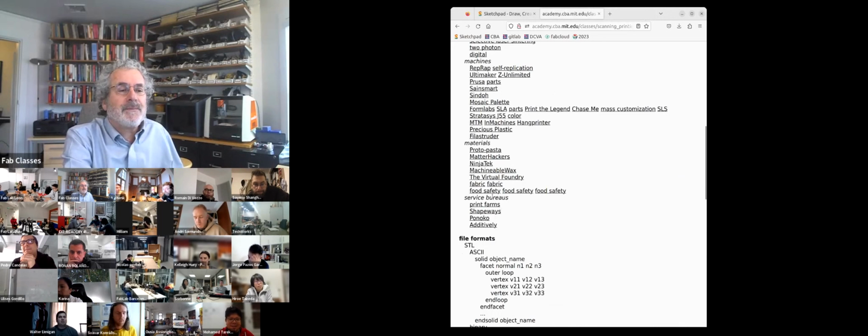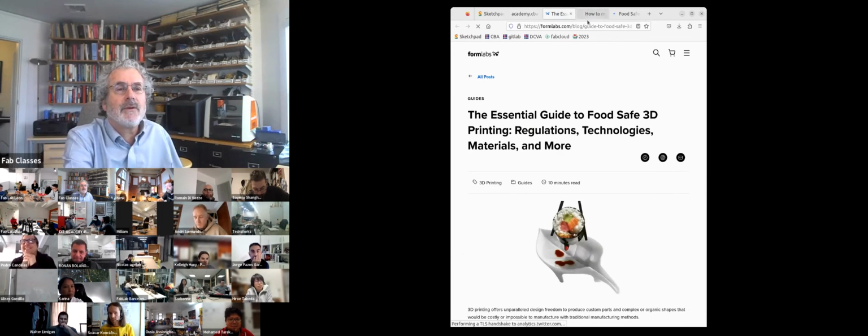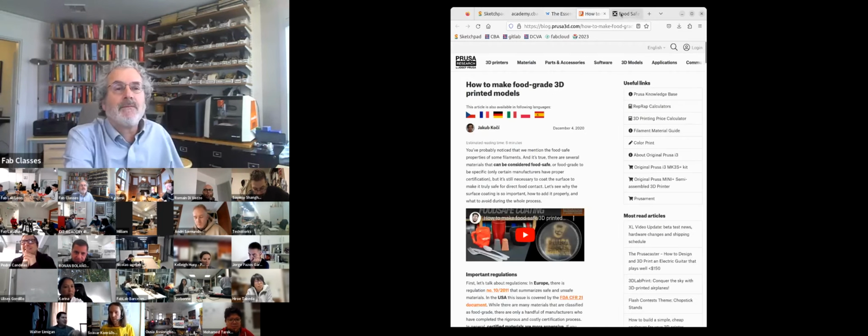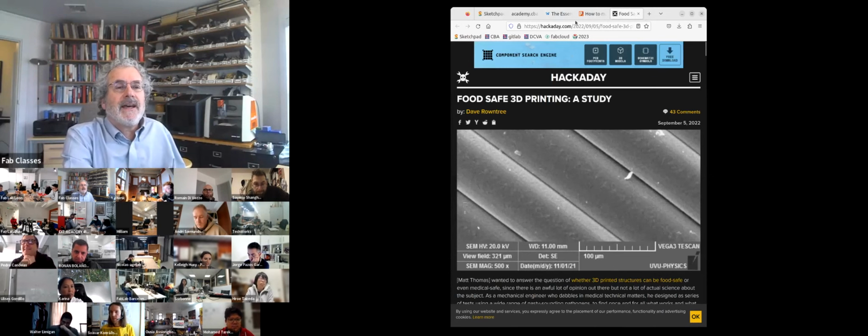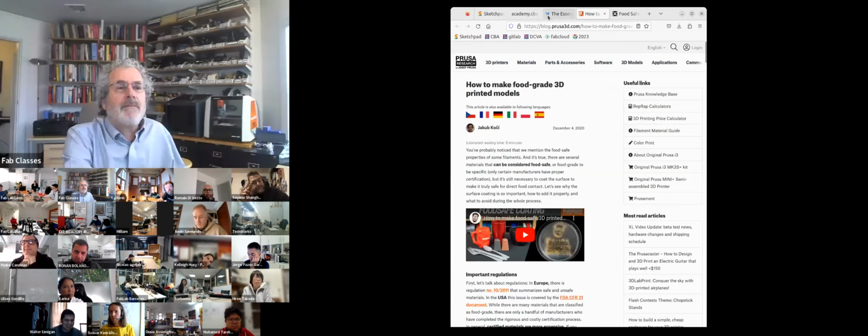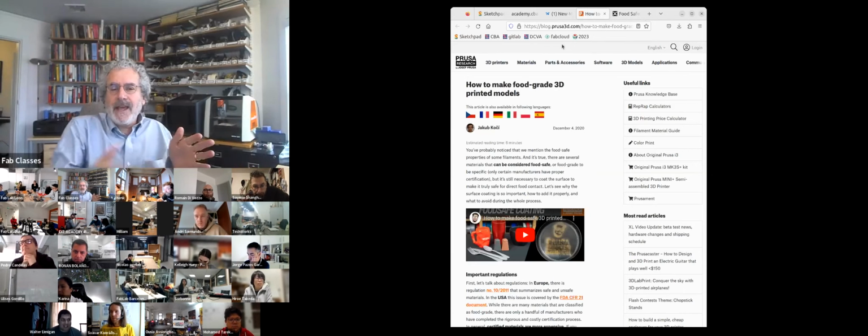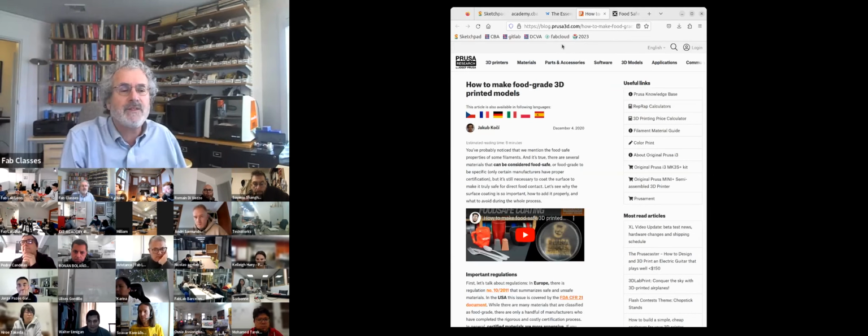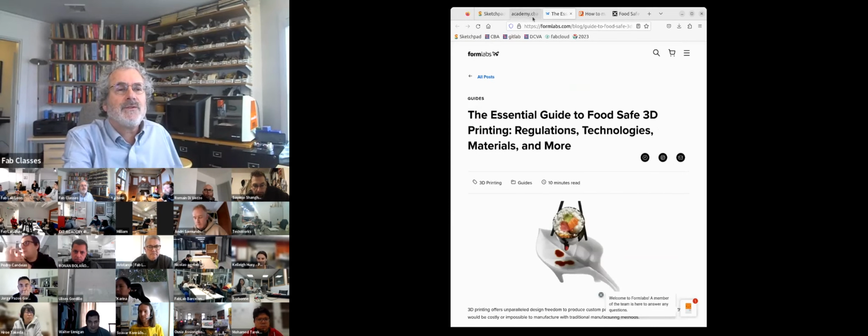Then food. You need to be careful with food. So this is a link from Formlabs. This is a link from Prusa. This is a Hackaday study. There are a bunch of issues with food. Printing food safe is like being kosher. The whole chain of producing your material, your printer, everything has to stay food safe. So this is a link to materials that are food safe.